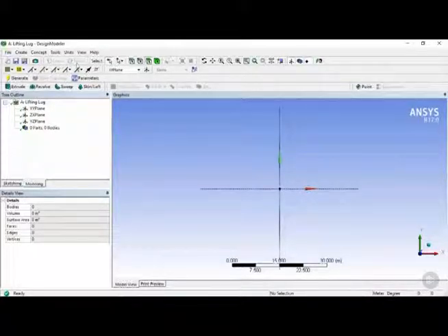We have here Undo, Redo. Next to that, we have the Selection menu. So here we can change, let's say, our select mode from a single select to a box select. This helps us select multiple objects at the same time. Here we have the selection filters. So here we can choose, let's say if we want to just choose a point or a vertex on a body, we would use this filter. If we just want to select an edge, we can click on this one. A face would be this filter. And finally, if we want to select bodies, we would use this filter right here.